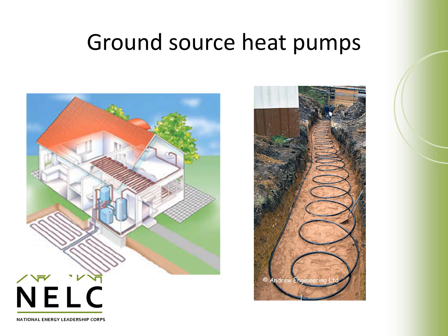In ground source heat pumps, the earth is used to exchange heat rather than outside air. Refrigerant is pumped through loops underground that are designed to be long enough to achieve a desired amount of heating or cooling. Ground source loops can be built through deep wells drilled vertically or by trenches and horizontal loops for the refrigerant.